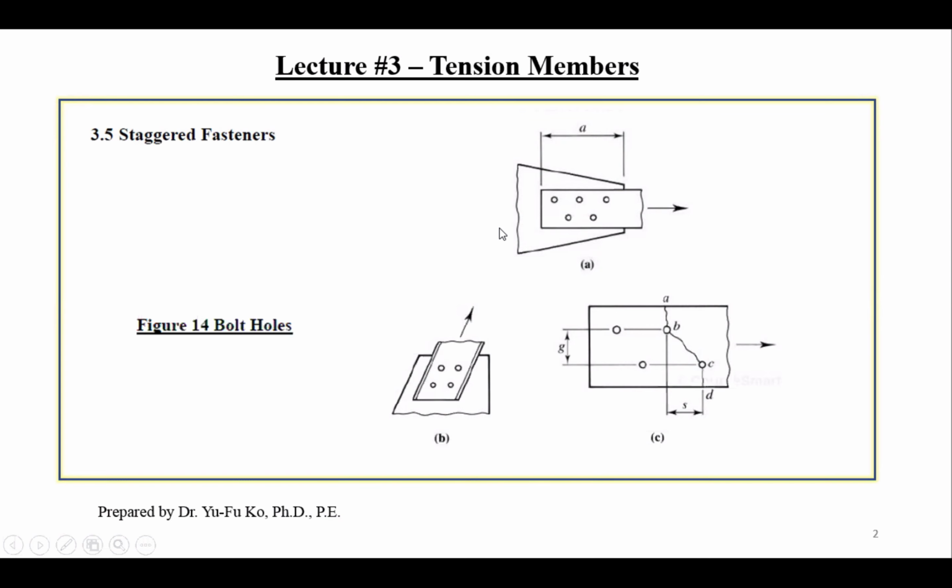And of course, it can also fracture like this. So you need to consider different failure paths when your bolts are staggered. That's the reason we need to consider staggered bolts in practical connections.